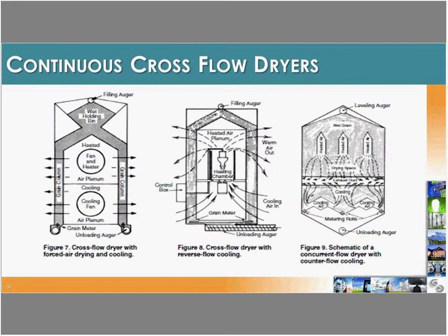So just to touch a little bit on the continuous cross-flow dryers, which, again, are very popular, but I said not to be the most efficient dryer out there. The first picture is showing the cross-flow horizontal dryer with forced air. So you'll see that it has a split air funnel in there where you have the cooling fan to the bottom and the heated air to the top.